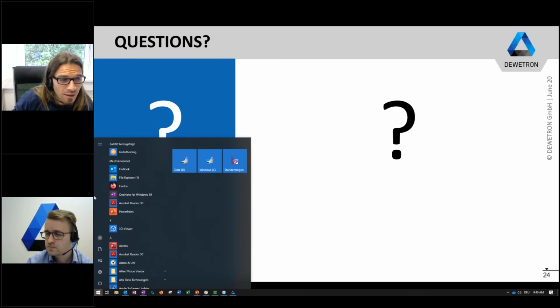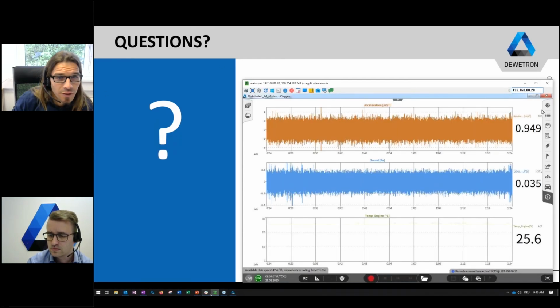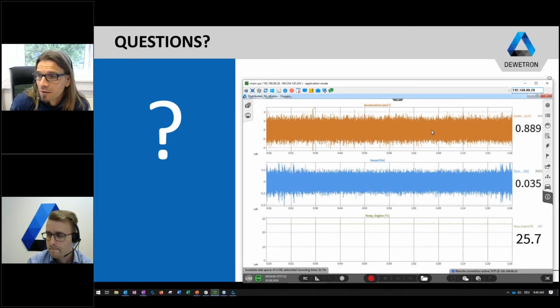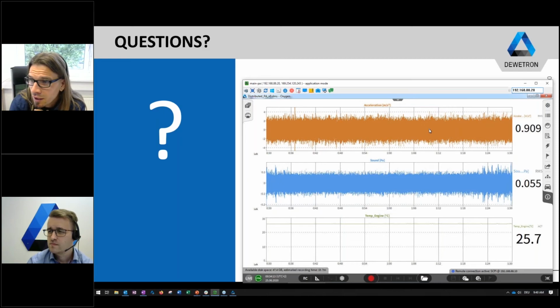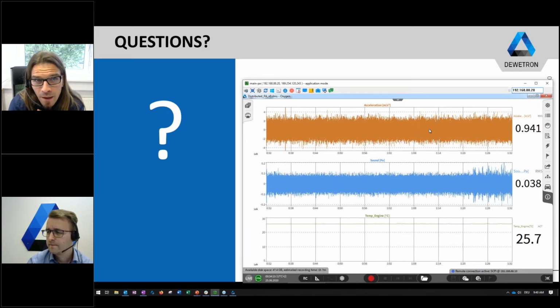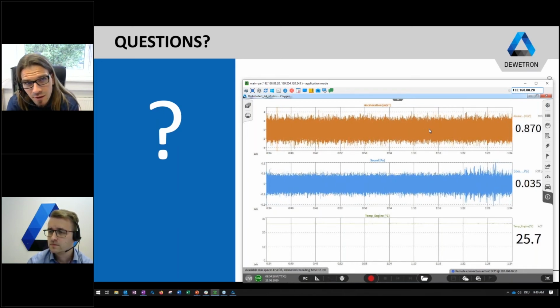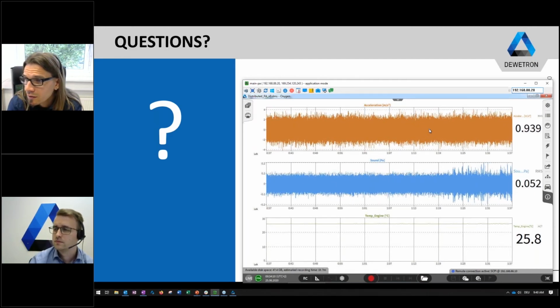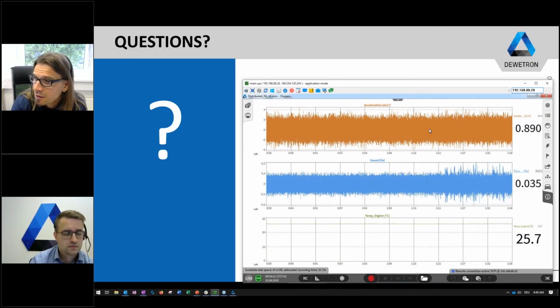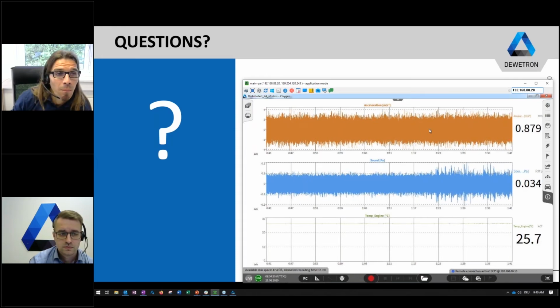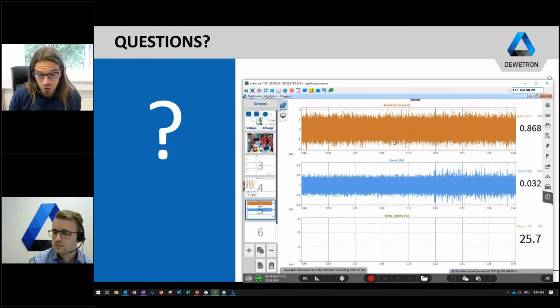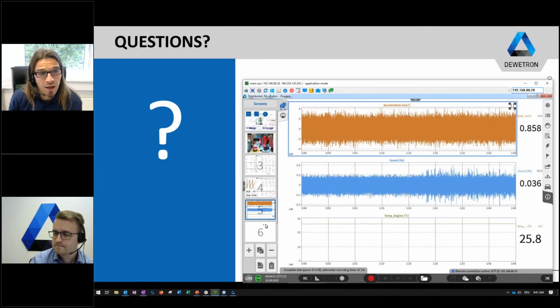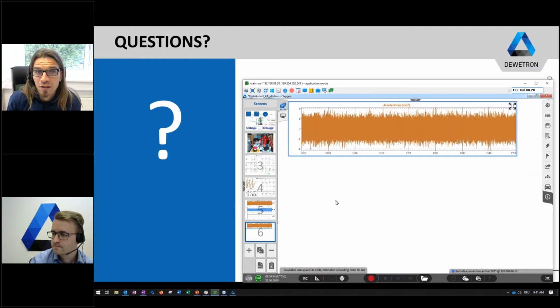Basically, yes. I already showed you here that we already acquire the vibrational data with the power, or with the system which also determines and calculates the power. You can for sure use this acceleration and this vibration data to do an FFT analysis in the post-processing, but I would recommend you, or I would also like to show you, that you can even do an online FFT calculation with the acceleration data.